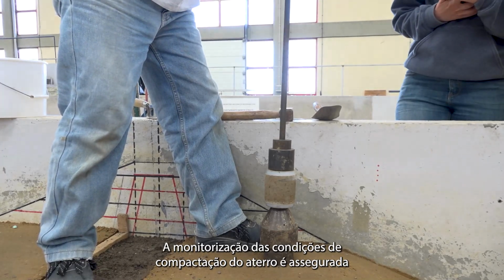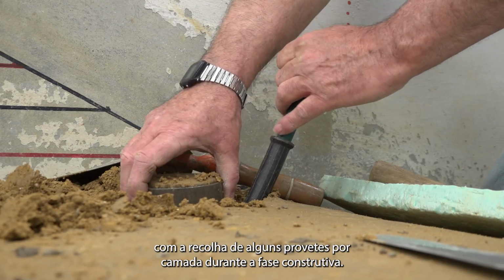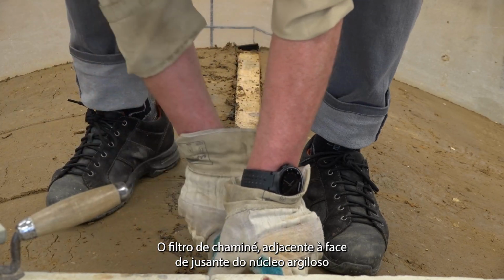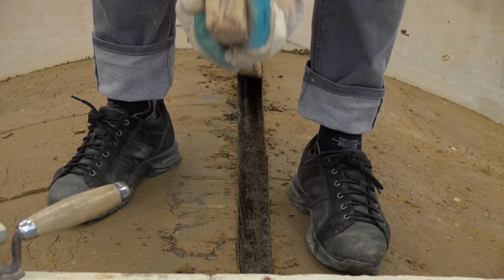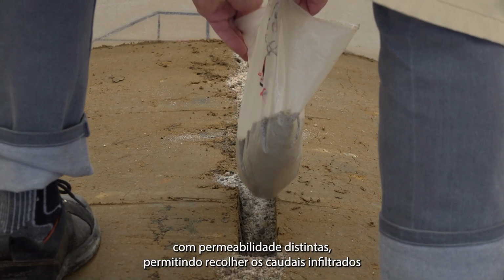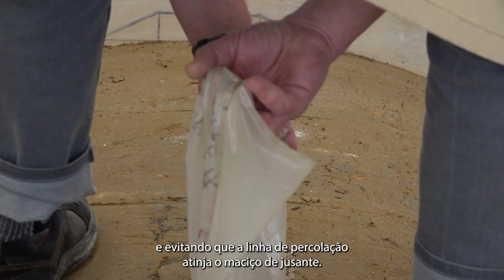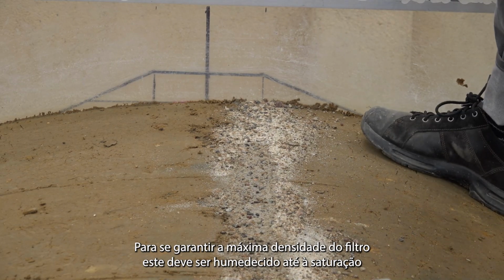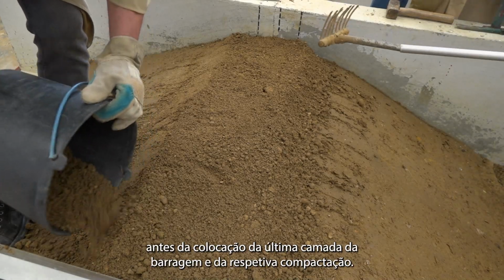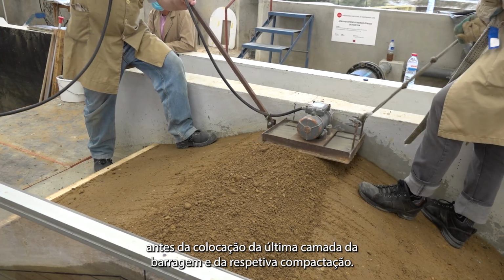Cores are collected from each lift to monitor compaction characteristics during the construction phase. The chimney filter abutting the downstream face of the impervious core is built as a sandy transition to collect the seepage and hence keeping the downstream shell relatively dry. After the last lift is erected, the chimney filter is wetted before compaction to achieve saturation and hence to provide the maximum density of the filter.